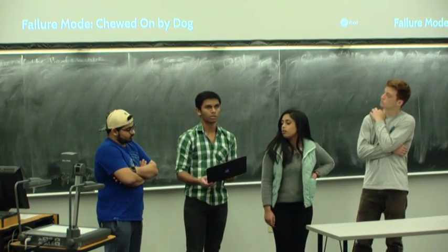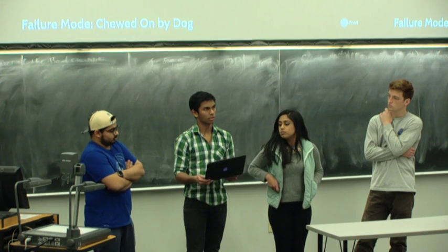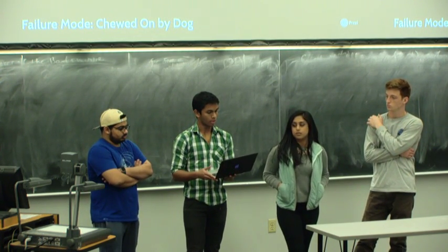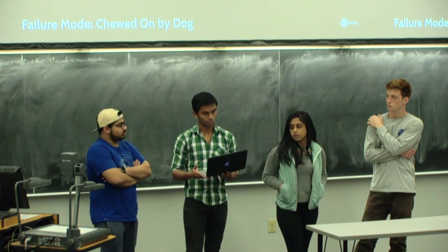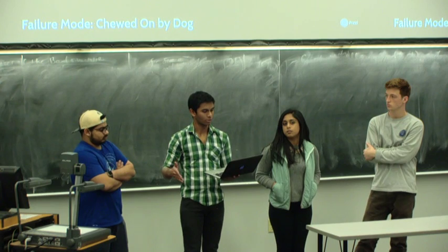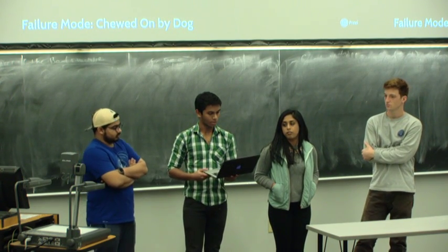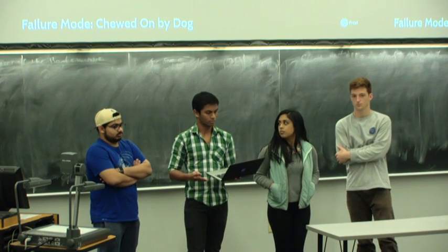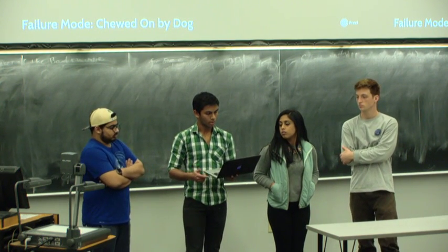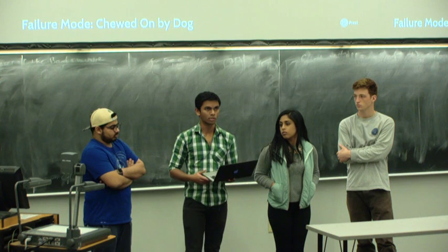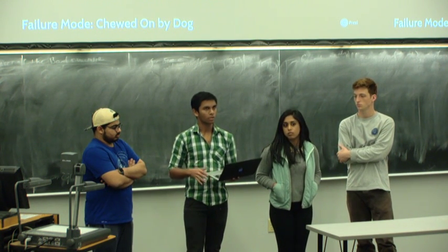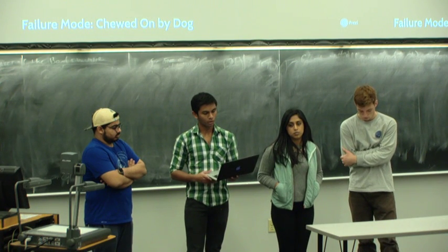And the last process function that we had was in the assembly and manufacturing process. Something that we thought about was, what if the seat didn't fit in the canoe? The potential effect would be, of course, you can't fit that particular seat in that canoe. The severity of that was 4 because you can easily just throw it out and build a new one. And the potential cause of this was that the machine that we used to build the seats wasn't set up properly.